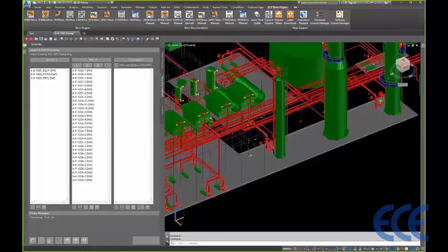We've had customers tell us that to rerun all of these ISOs through Isogen inside of Plant 3D could take 3.5 hours to get that done. As an entire test, I ran through the entire project here with ISOWorx, and it took roughly 3 minutes to be able to update all 256 drawings here. Much faster than having to rerun them if all you need to do is post-process this data.